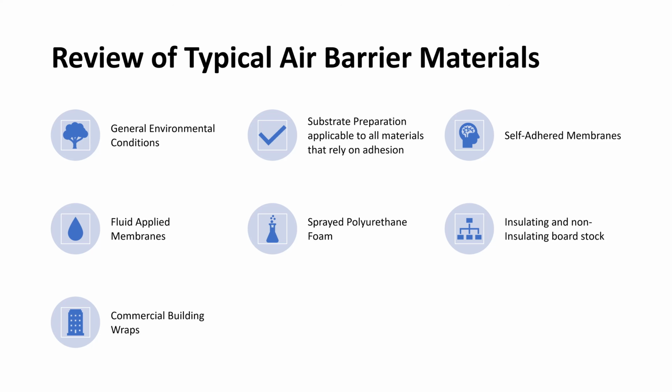Now there could be more air barrier materials out there, but these are the ones that would be considered the more popular ones when you're dealing with commercial and institutional construction. When you're getting down to the residential side of things, that's typically where you're going to find more of the house wraps. We're seeing some fluids becoming a little bit more popular. We're seeing some self-adhered becoming a little bit more popular, but really the house wrap, building wrap tends to be the biggest market share when it comes to single family and residential type homes.